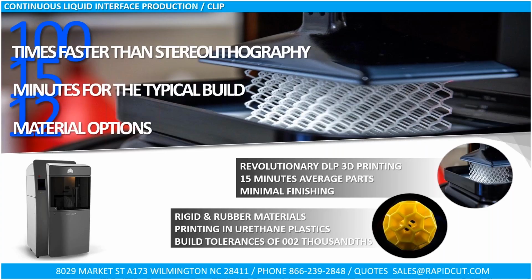To put that into terms, once this process is matured, you could very easily, call it 4 o'clock in the afternoon, have a part shipped out the same day, FedEx, built, finished, etc. With an SLA at best, we need to start at the beginning of the day to accomplish something like that. The average build for an SLA part is about 4 to 6 hours, 15 minutes for CLIP. And there's 12 different materials available, some very exciting urethanes.